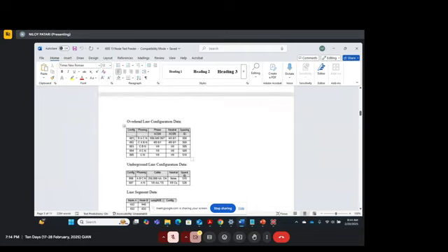So there is this line code. There is this particular line which is coded as 601. It can be 1001 also, right? But they have just given it as 601. So this overhead line has all ABC phases as well as the neutral, and it shows the line configuration, right? So it's an ACSR type of conductor, and the spacing ID is given. All this spacing ID, everything will make some sense in a bit.